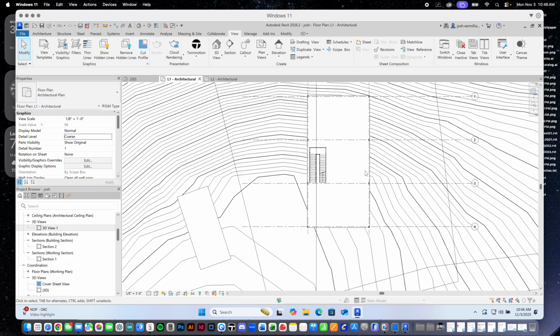Walls, exterior. So we're going to do some solid walls along the east and west sides, right? Surprise, we're in the desert, and we don't like the east and west sun so much, right? It's great for viewing outside for sunrises and sunsets, but it makes terrible glare, internal heat load, etc. It's hard to control. So we're going to make some solid walls along that east-west. Don't worry. I have some very special custom family windows that we'll put in later, next week at some point. I'll give you the family and we can look at how they're made and see how you can make your own window family if you'd like, to frame very specific views.